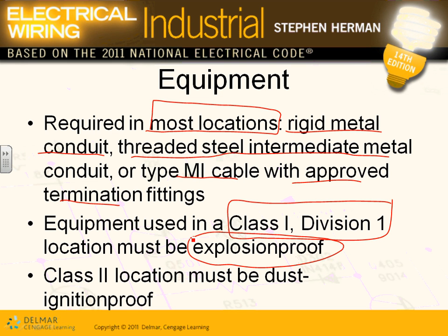You turn the circuit breaker on manually or automatically and make a spark, and you have an explosion inside this circuit breaker panel, box, or contactor, and two things could happen. First of all, the integrity of the piece of equipment stays intact; it doesn't explode into pieces. Number two, the outside temperature does not exceed the igniting temperature of the surroundings, so it doesn't create another fire around it. So that's a major thing.